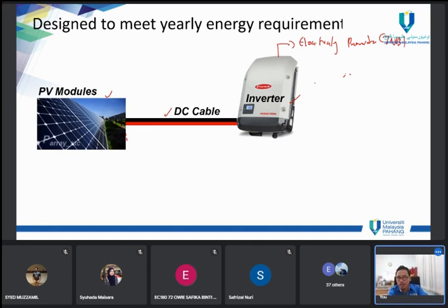First of all, when we have the PV modules, we are going to have the value for the P array STC. How many modules you have will reflect the P array STC. If we have 10 modules, 240 watts per module, then 10 modules equal 2.4 kilowatts of power. That power is the P array STC.